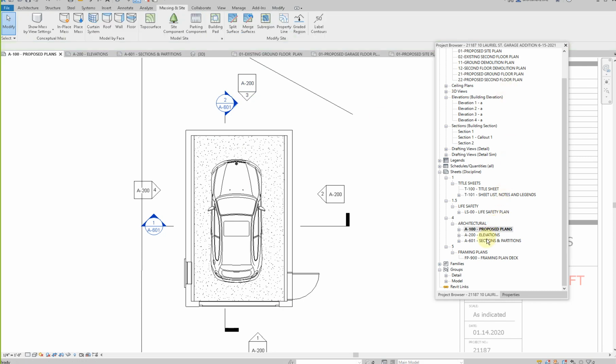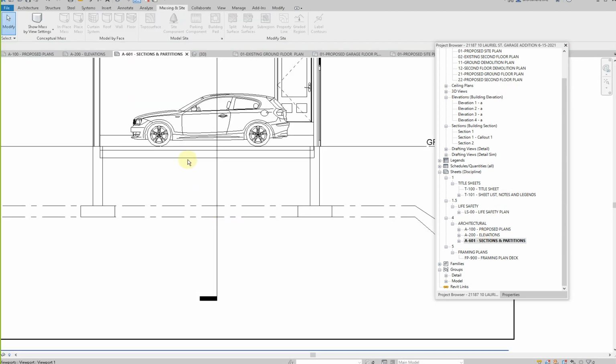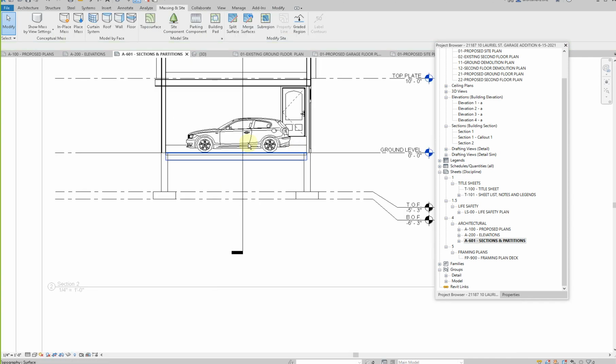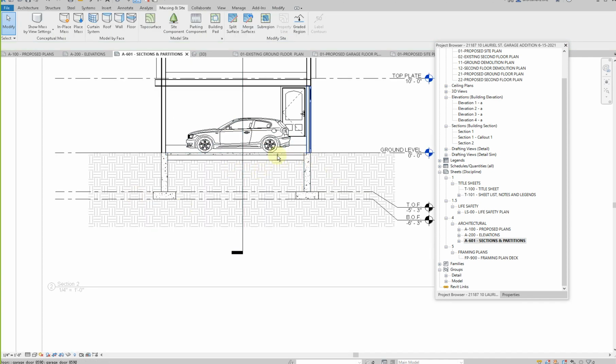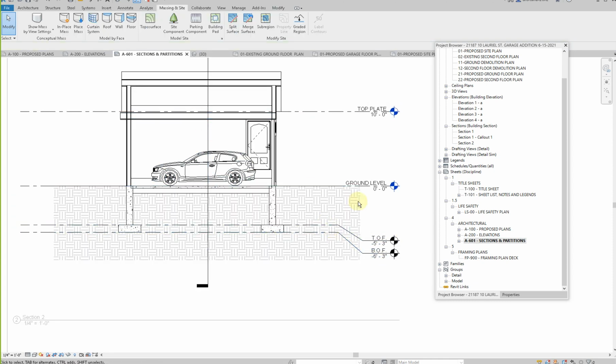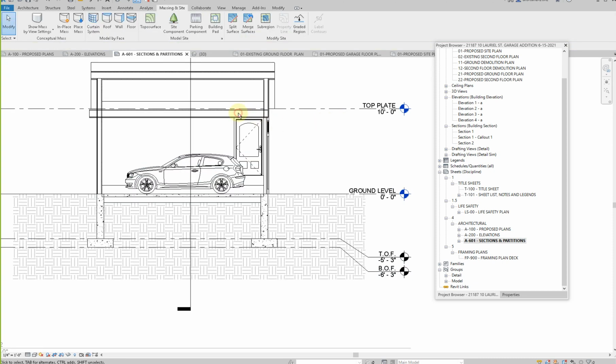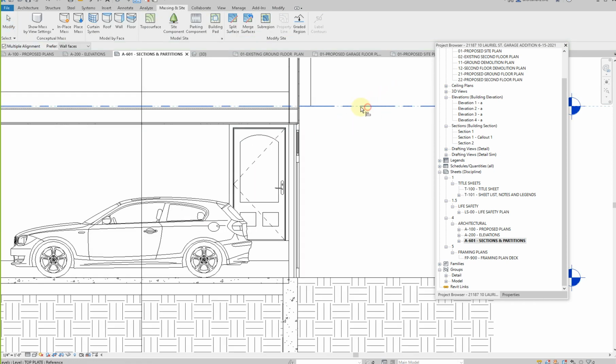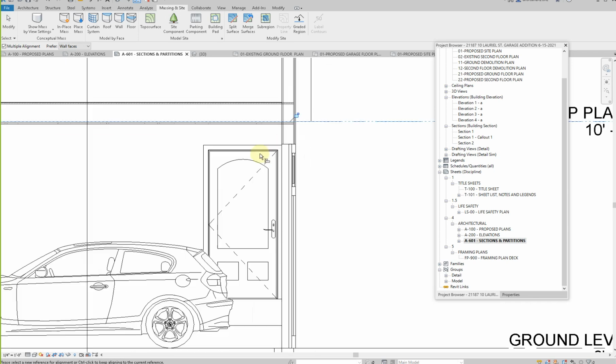And then if you go to your sections now you have this pad. I typically just hide it, but at least we don't have the dirt going right through into our space. Okay, so this is good. So far so good. We gotta make sure this floor is sitting on the top plate. He needs to sit on the top plate, literally sit on the top plate.